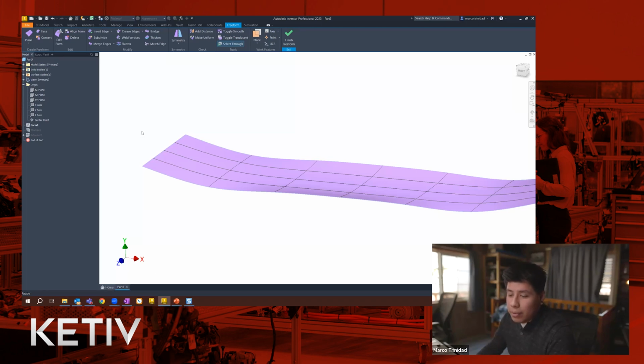Yeah, so for any surface that I have, it's used almost like a sketch, since it's a tool to then build geometry down the line. So the surface ends up being a child of the feature that I use. So if I delete the child, I end up deleting the feature itself. This is a good note to make.